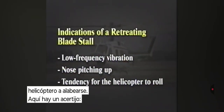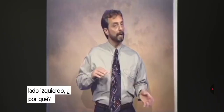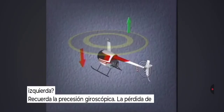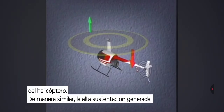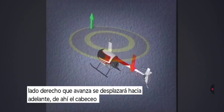Here's a brain teaser for you. If the rotor disc is stalling on the left, why is it pitching up instead of to the left side? Remember gyroscopic precession? The stall won't become noticeable until it rotates another quarter turn towards the rear of the helicopter. Similarly, the high lift generated on the advancing right side will move to the front, hence the nose pitch up.